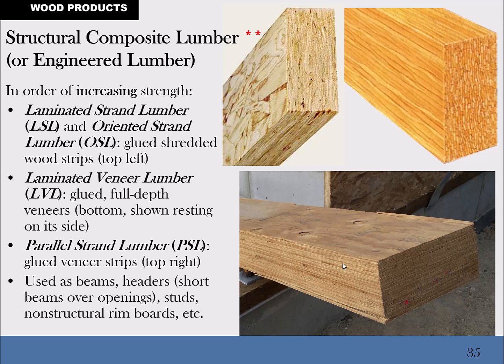No, it's actually one solid piece of engineered wood material, where the veneers have been glued together just like they do with plywood, except that with plywood, every other layer is rotated 90 degrees so that you get more strength and you don't have splitting. Here, for strength for carrying loads as a beam, all the wood grain levels run the same direction, end to end along the long length. So that's LVL, or laminated veneer lumber.